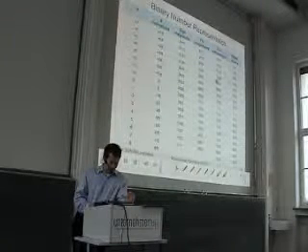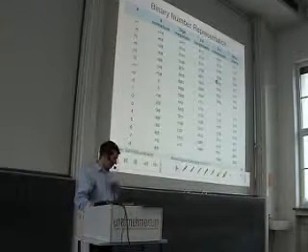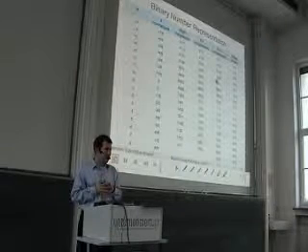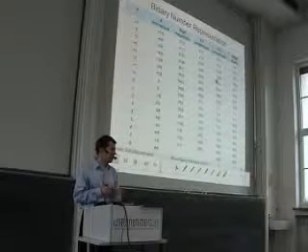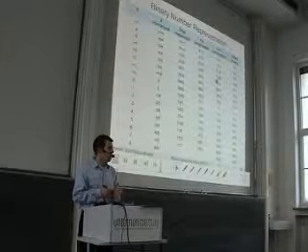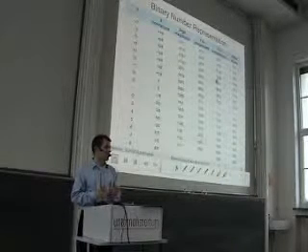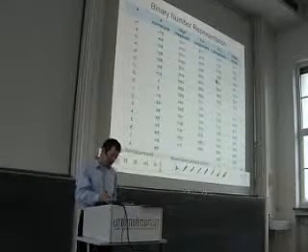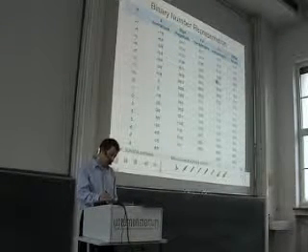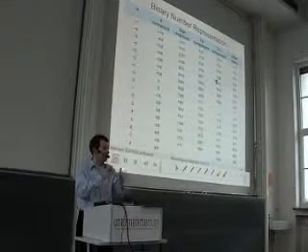One number system that is often used is the so-called sign magnitude. Again, the MSB indicates the sign of the number. So a 0 means a positive number, a 1 MSB means a negative number, but then all the remaining bits indicate the absolute value. Okay? So all other bits except the MSB are the same for positive and negative numbers. So we have a sign bit and we have an absolute value.